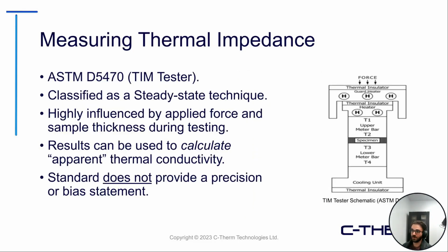So I just want to take a note on measuring each of them, and I'll start with thermal impedance. This won't be the focus of our session today, but I did want to touch on this very briefly. When you're measuring thermal impedance, typically this is done using a TIM tester that conforms to ASTM D5470. We can see a schematic diagram, taken from the ASTM standard, on the right. It's classified as a steady state technique.